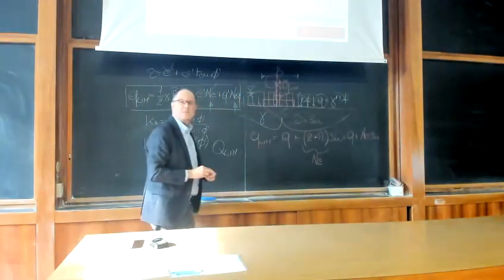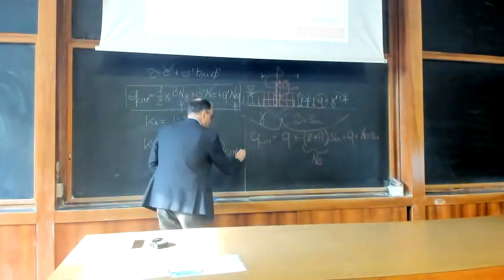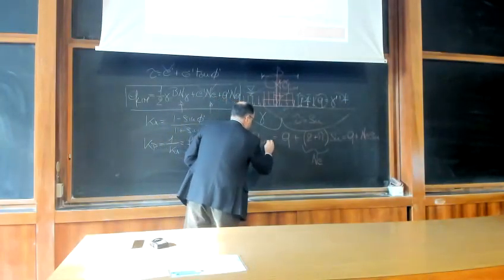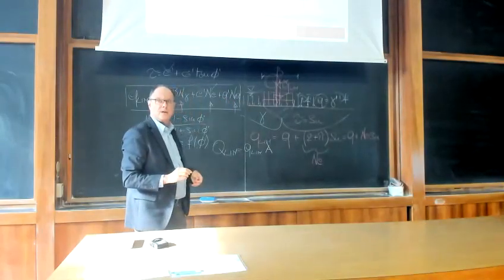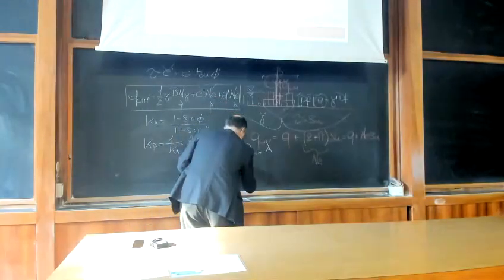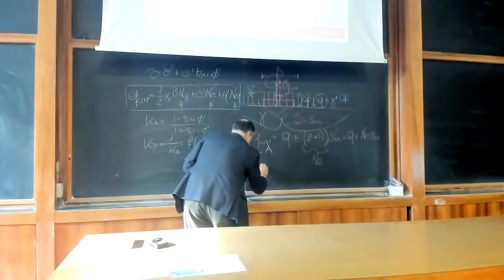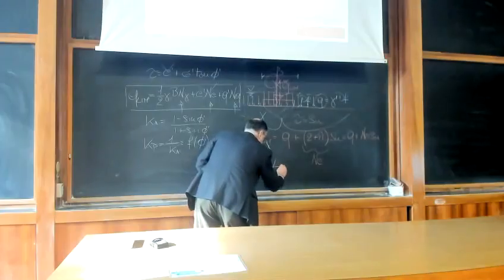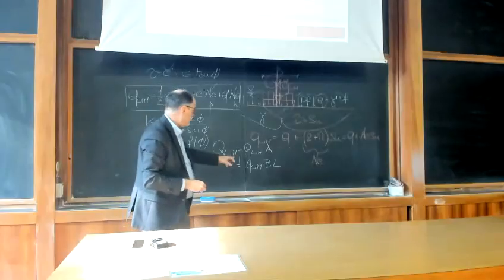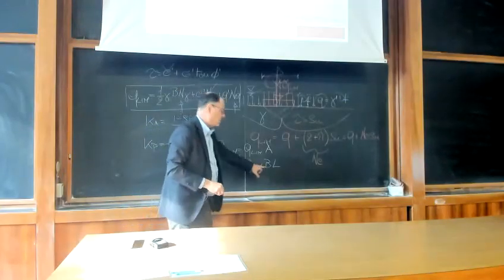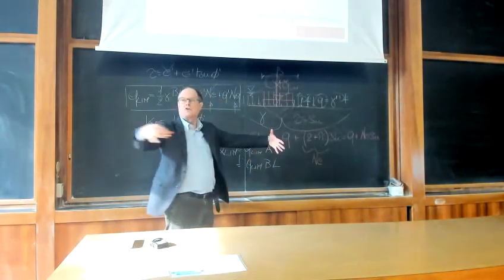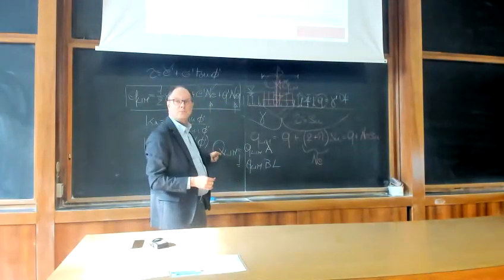The Q limit is this pressure, what you get from this expression, times the area of your footing. And if you consider that your footing is a rectangular footing, for example, you have your q limit times B, which is the footing breadth, times L, which is the footing length. So it is obvious that the load depends on the area, because this is the pressure. You multiply by the area, the larger is the footing, the higher is the load.